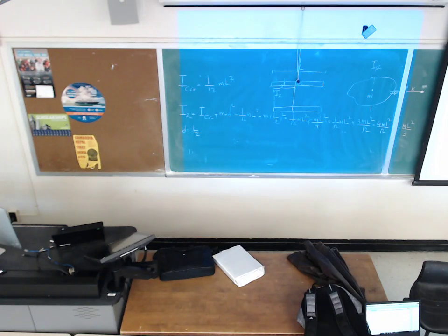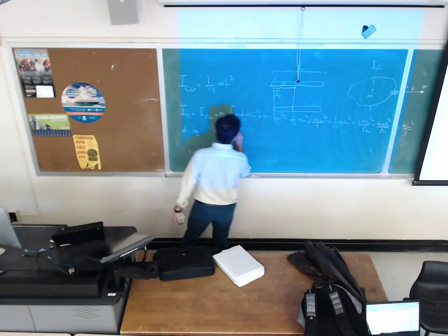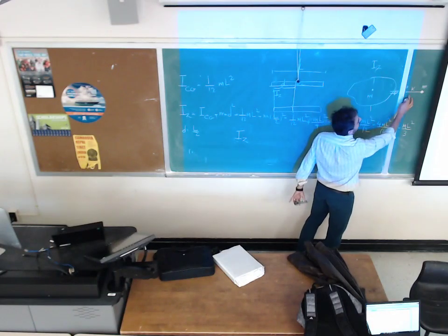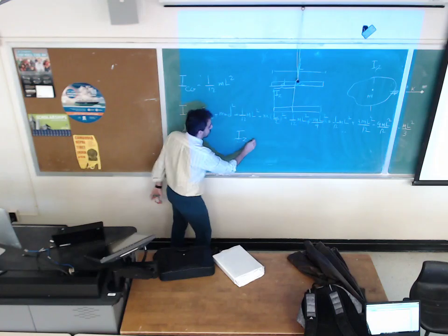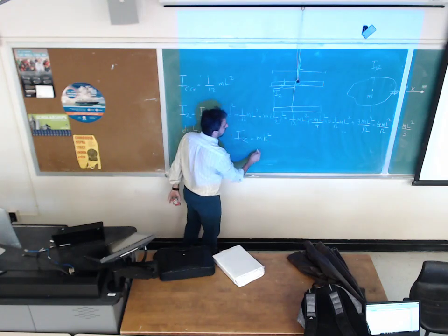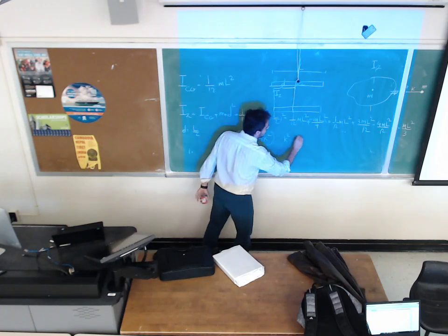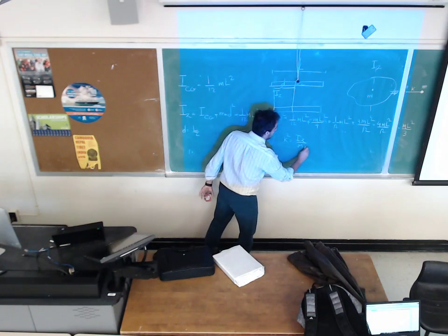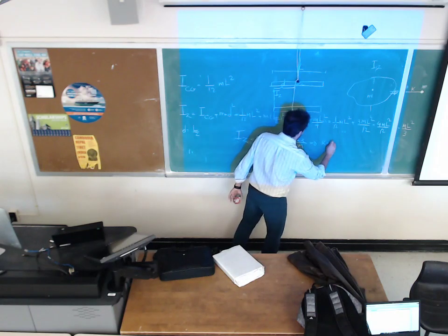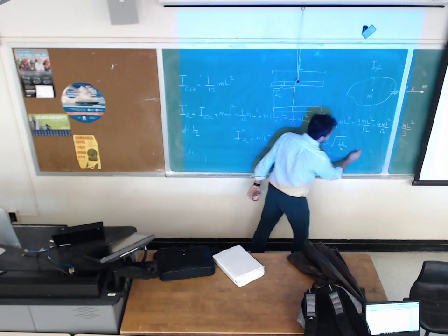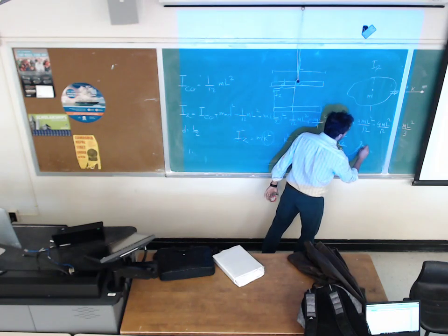So what I'm going to do, I'm gonna set this equal to the Iz. The mass moment of inertia for this system is Iz. I'm setting this equal to mass times k squared, and I'm solving for k. k squared would be Iz divided by m, and k would be the square root of Iz divided by m. We call this k the radius of gyration.